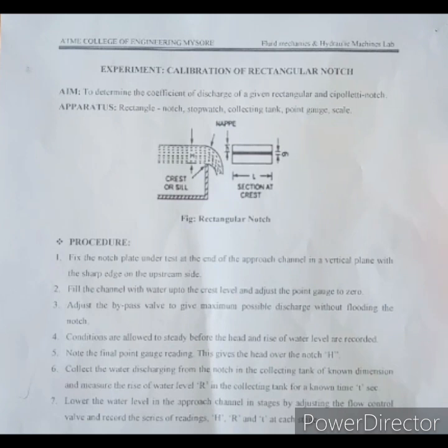Notch is an instrument which is used to determine the discharge over an open channel. There are different types of notches based on their shapes. It can be classified as rectangular notch, triangular notch, V-shaped notch, trapezoidal notch and Cipolletti notch.